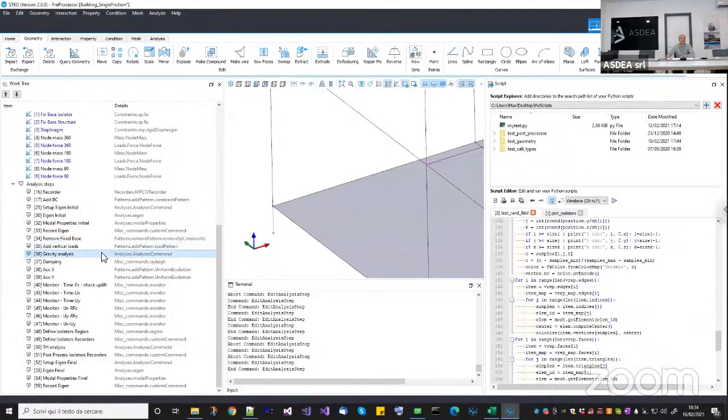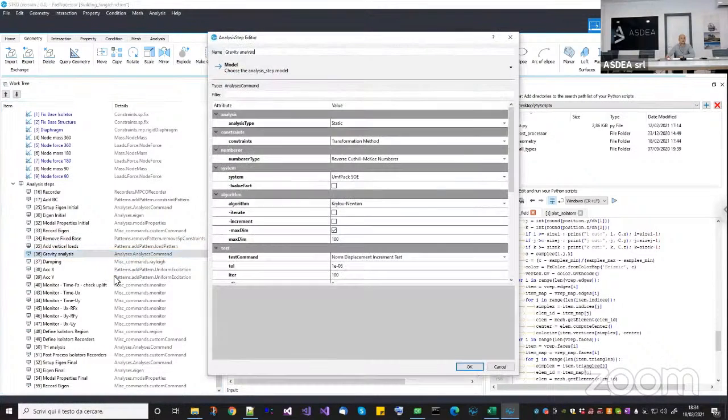After we have the vertical loads, we can run a static gravity analysis. So open this one and you can see that it is a static analysis, simply a transformation method. Oh, by the way, all the settings in all these analyses are the same. They will just change from static to transient when we are going to do the time history analysis.